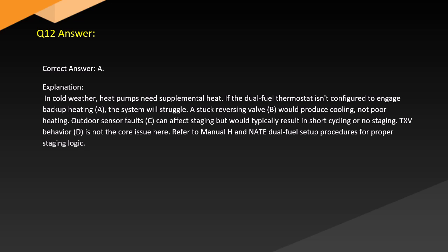Outdoor sensor faults (C) can affect staging but would typically result in short cycling or no staging. TXV behavior (D) is not the core issue here. Refer to Manual S and NATE setup procedures for proper staging logic.